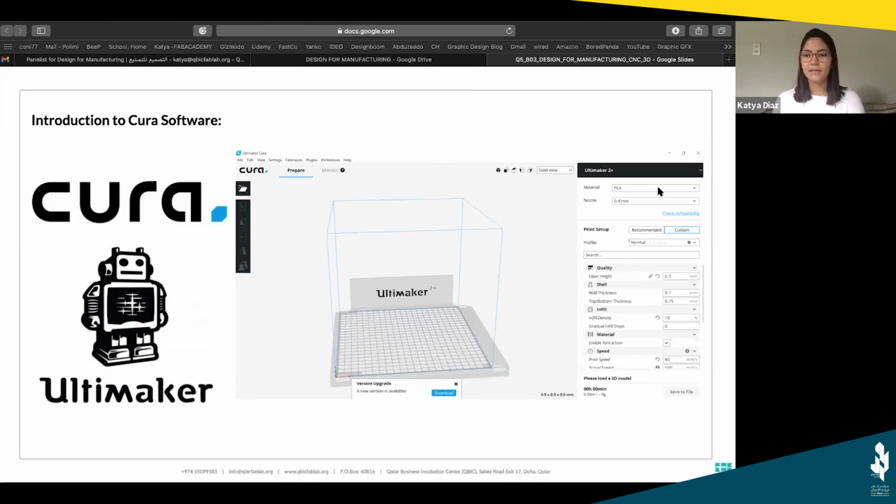In my case, I will recommend you to, most of the time, use 30% infill in here, because we made some tests at the lab, and after 30%, it's super dense, which means that the extruder has to go more and more times in the same space. So this also increases the time of the print and the material, and with 30%, we already get a really dense model.